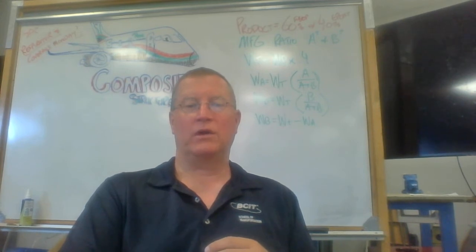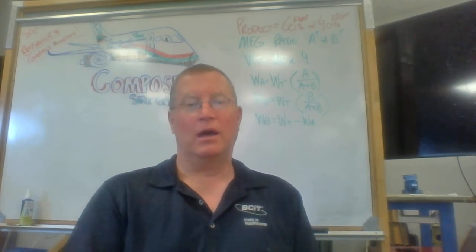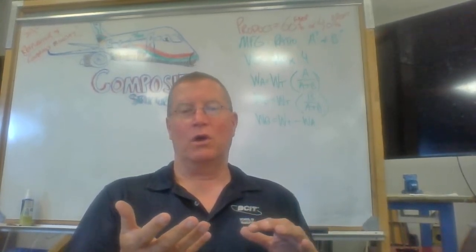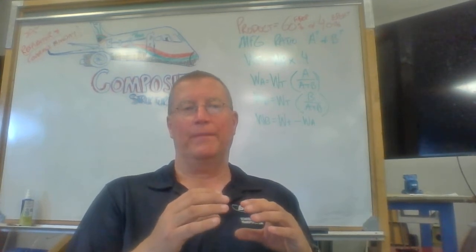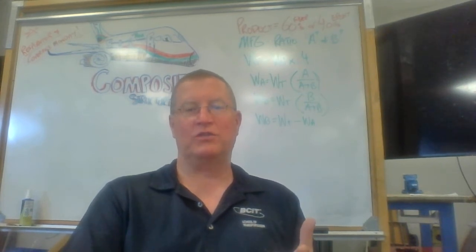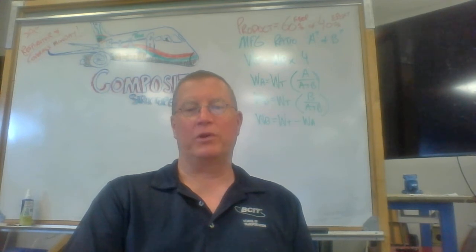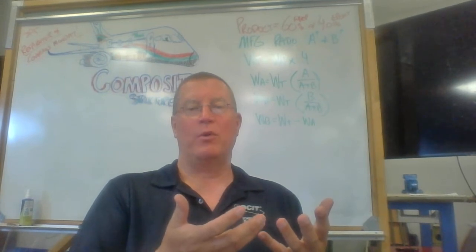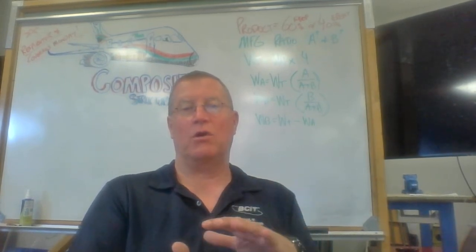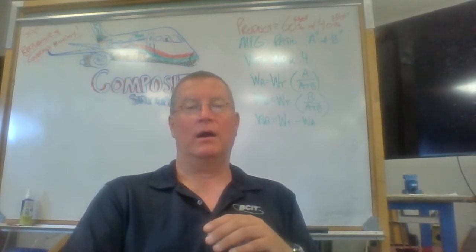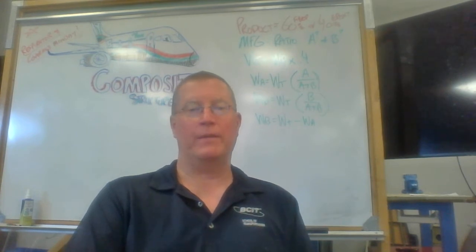And so that's important. Understand the 2 different ways of building a composite product. It can be strength through layers, so laminate construction, or rigidity through box design, or sandwich construction. Each has its advantages depending on what it is you're doing with it. And so principal strength comes through laminating, through multi-layers to gain strength, but we can also have a relatively strong product that has great rigidity through a core and layered surface top and bottom, right? Creating that box section which gives us the rigidity and strength.